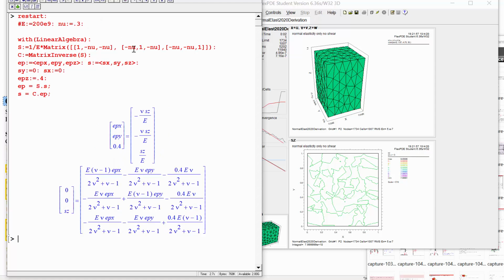So what this tells us is not really easy to see from this formulation, from using the stress times the strain, because the strains are mostly unknown. There's a lot of unknowns in there. But using this formulation, it's more obvious what's going on. You can see that the z stress needs to be 40% times the Young's modulus. When we know most of the stresses, then it's usually easier to use the compliance matrix multiplied by the stress to see what the strains are directly.